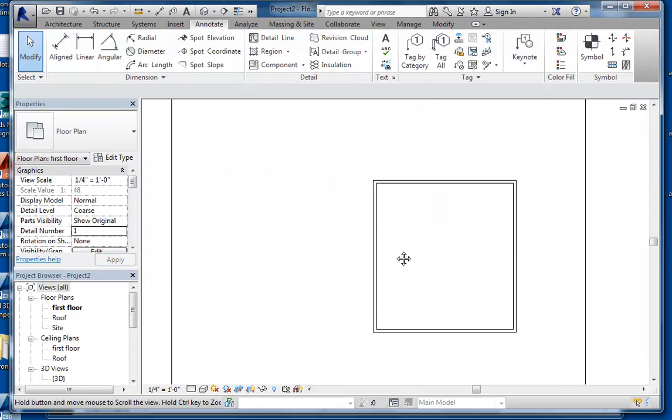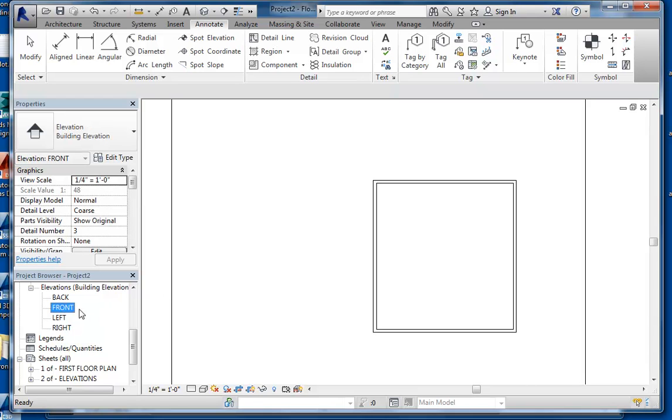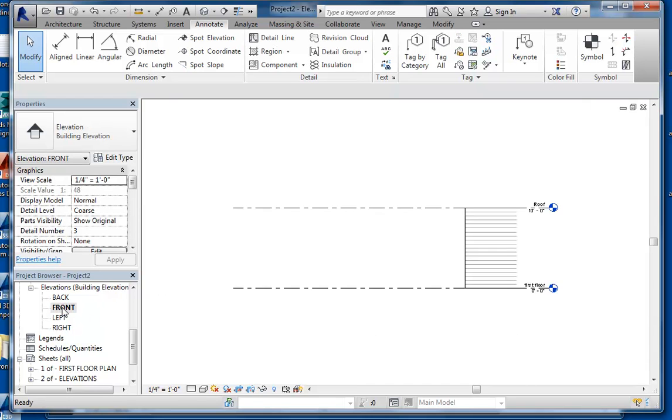Now, one of the things that we did when we talked about wall sections is we came up with wall heights based on stacking our rough opening dimensions for our door and our header that we needed and our top plate. You're going to do a similar thing with this, where you're going to set your wall dimensions for that roof level. I'm going to switch to an elevation view by double clicking on it here.